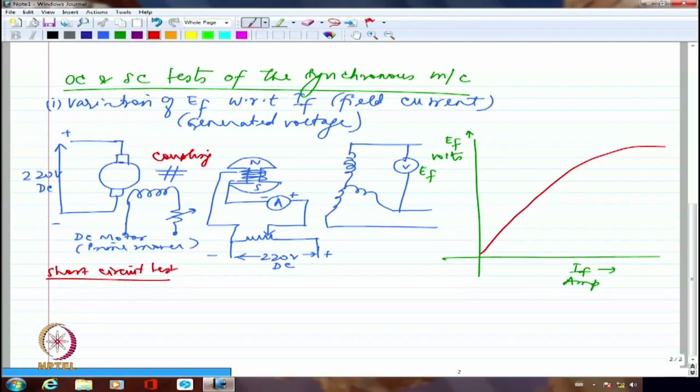So if I want to have speed control, I have to have frequency control. No wonder we have become a very important commodity, power electronic engineers, who make inverters, who basically generate variable frequency. So all the synchronous motors are now able to run at variable speed if I am able to generate variable frequency. That's the reason. Okay?